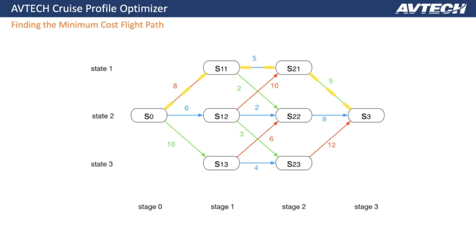By utilizing an accurate aircraft performance model, the cost of each available step can be calculated, and in each step there are decisions to be made, whether to remain on the level, whether to climb to a higher level, or whether to descend to a lower level. And combining all these steps, looking at all the combinations, this algorithm is really finding a true global optimum, which minimizes the costs. And we here talk about the equivalent fuel cost, which is the cost of fuel and time combined through the cost index.